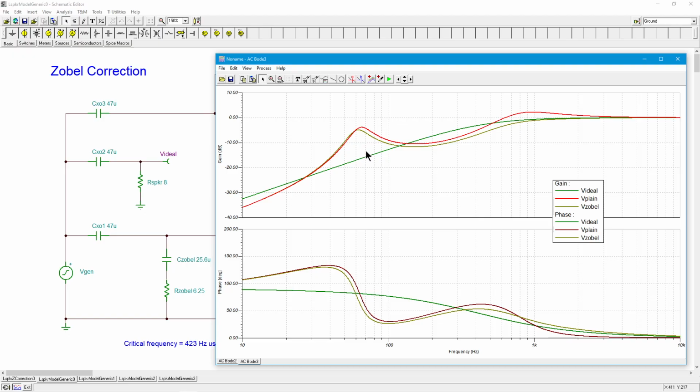We had that big resonant peak around 70 hertz. So this cap is not working against 8 ohms at 70 hertz. It's working against, it's up here behind the graph, 30, 35 ohms. So the amount of loss that you get is nowhere near the same. And we see this rise. So clearly we don't want that.